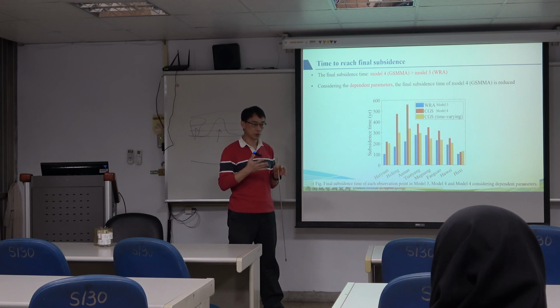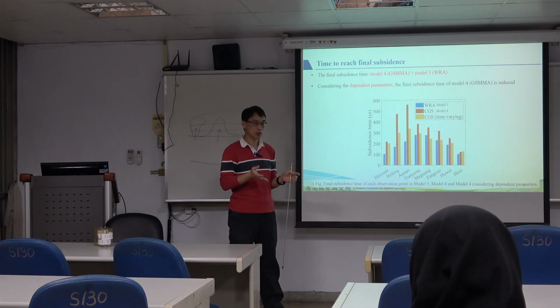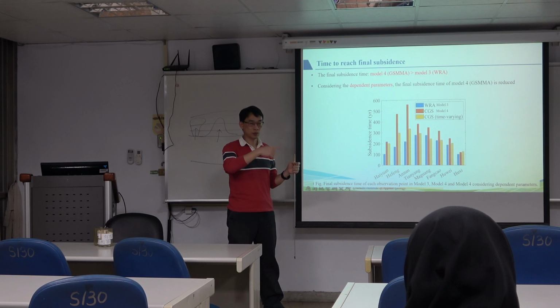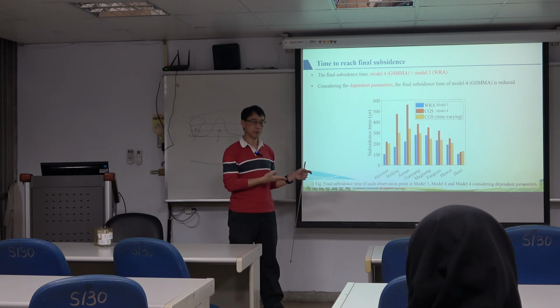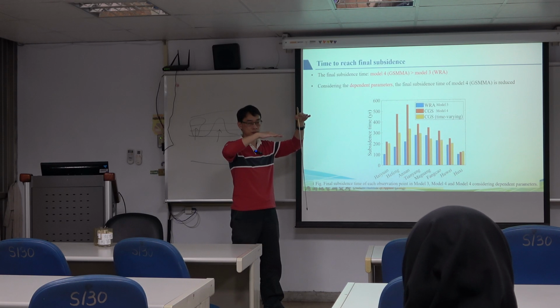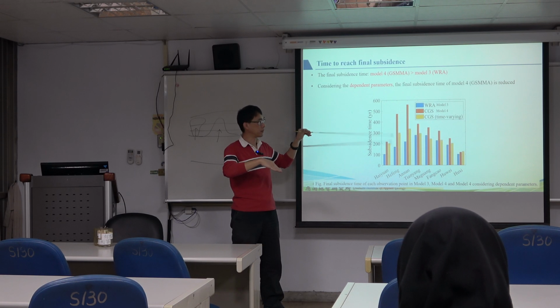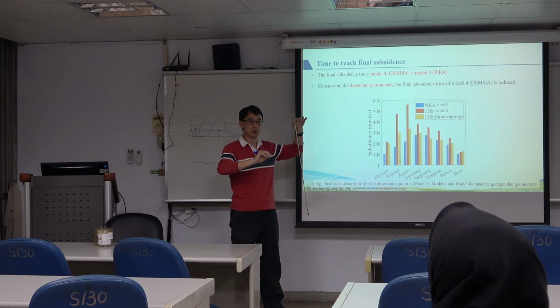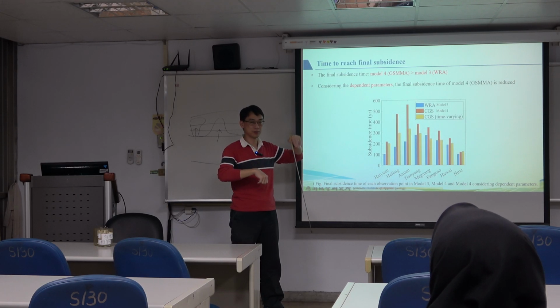That means if you do not do any work and you just stop pumping, like right now we see the water levels are the same, stable, you cannot solve the subsidence problem. To solve the subsidence problem, you need extra water inside to increase the water level, because the past was this level and right now it's this level. If you do not let your water levels approach your original levels, it takes 500 years to reach the final compression.